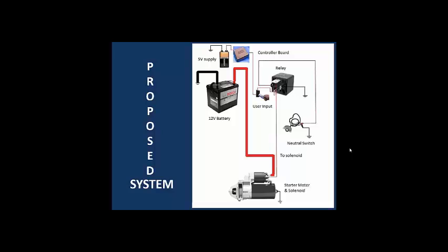After the engine has started, the starter motor should stop rotating, or else it will draw a large amount of current from the battery and the battery will get depleted. Or if the starter motor is still engaged, the engine will rotate the starter motor at a very high speed and there's a chance of the starter motor becoming damaged. So we'll be using a neutral switch, which indicates that the starter motor cannot start when the car is in any gear except the neutral gear.